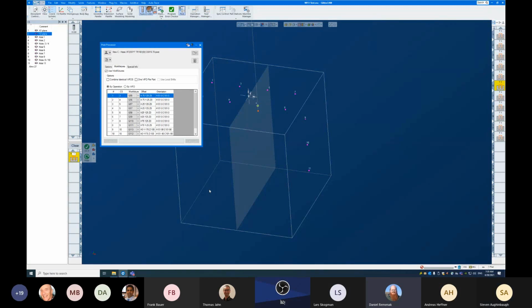I think it's technically a bug, but it's something that we've had to live with for a long time, and it's kind of intrinsic to the way Tool Edge works, in that we have to do this trimming when we encounter material with the edge of the tool, and we have to do it late enough that the entries and exits are already applied.